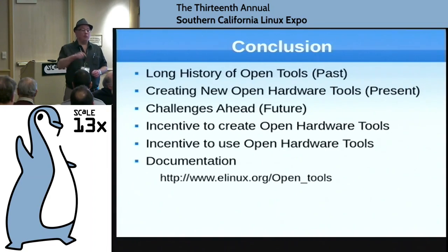Yes, because the reference design is only a guide. Usually it's done as a block diagram, and it's not a physical implementation. Now, if you copy exactly their reference design and put it directly on there, then that would be incompatible. That's the biggest thing, because you're copying their reference design. If you're just copying a design note that says, be sure and use a 12 picofarad cap on this signal, that's not an issue. Yeah, absolutely.